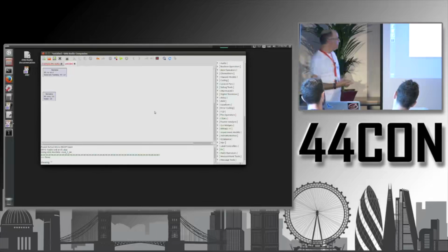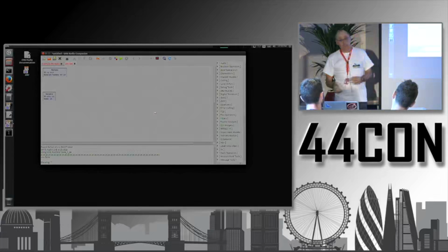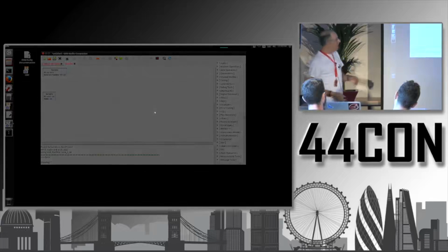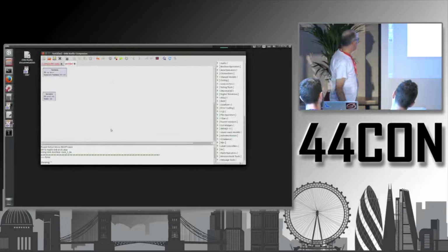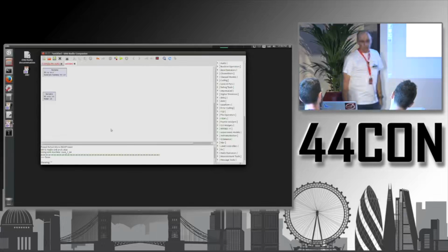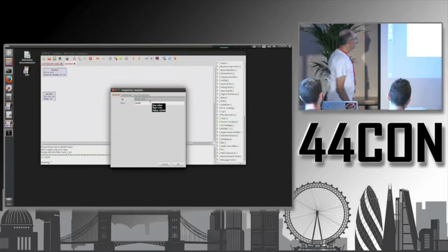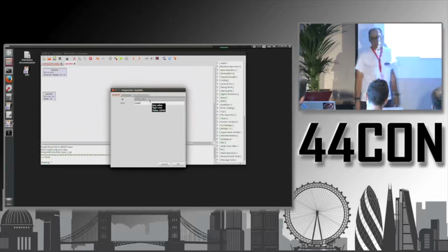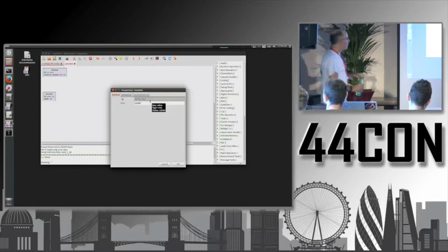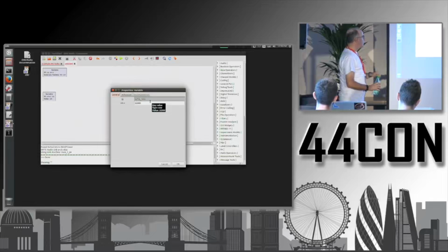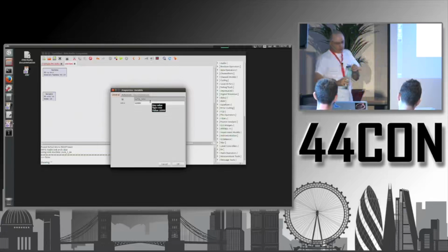So you have to sample at a speed that is high enough for what you're going to capture. And that is the purpose of this variable, the samp rate. You can double click this and you can see that it is set to 32,000. That's the default. But that is way too low for analog radio, for the FM radios we are going to capture.